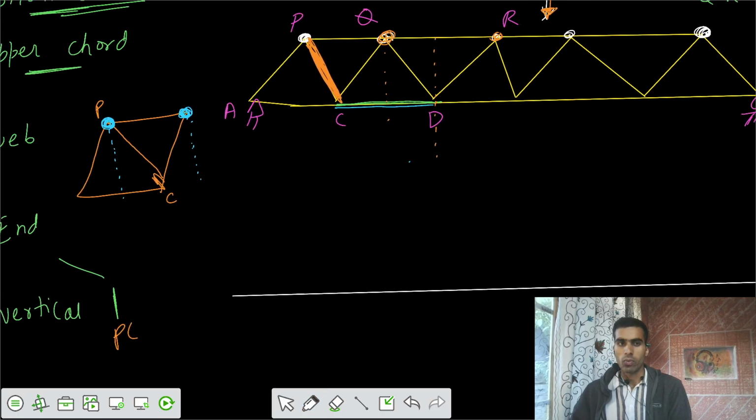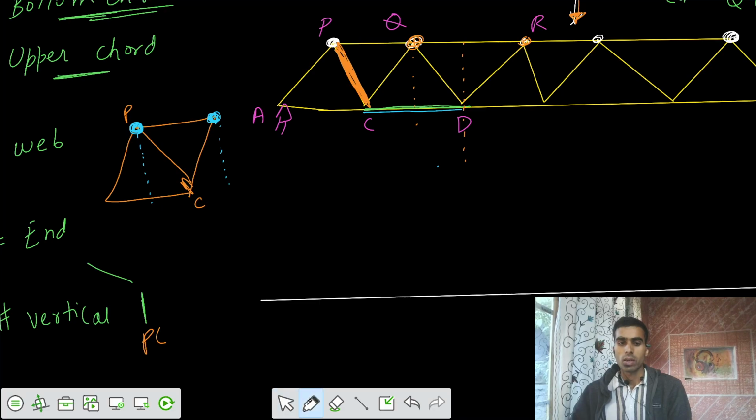Now you take the triangle, and the P gets developed at this location, and this is A by L, and this is A by L, D by H, A by L, D by H. So we got that. Out of these four joints we are having, which are the two which have loading? I would say one of the joints is P and one of the joints is Q that are having the loading. So our critical ordinates or points would be P and Q in the ILD.